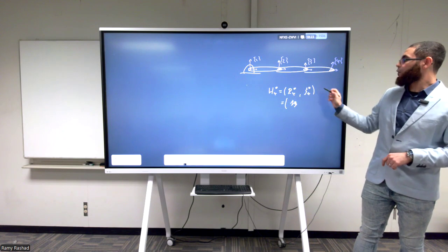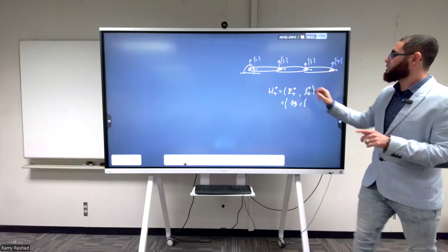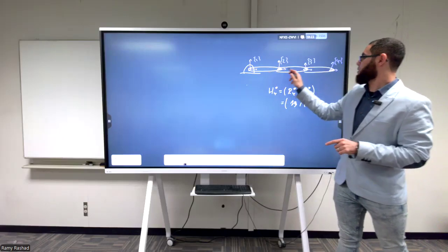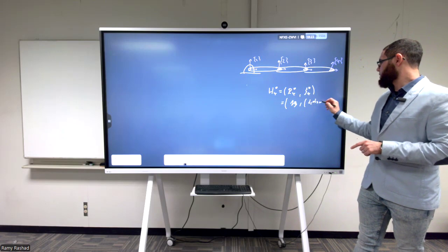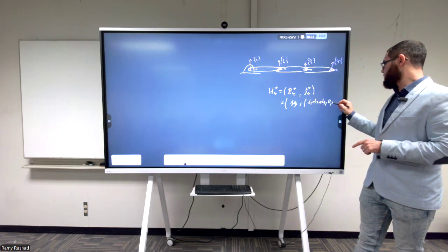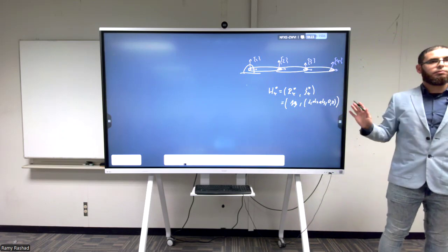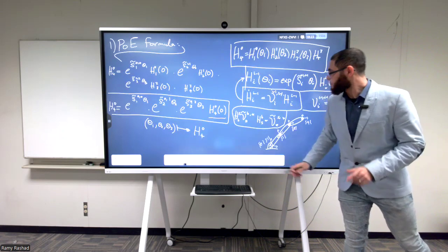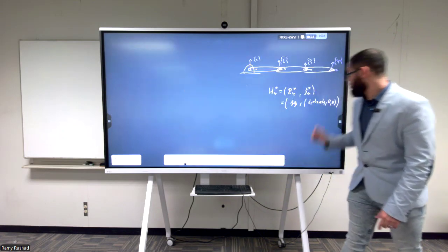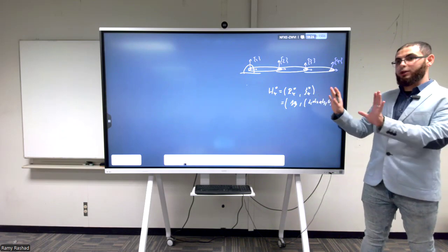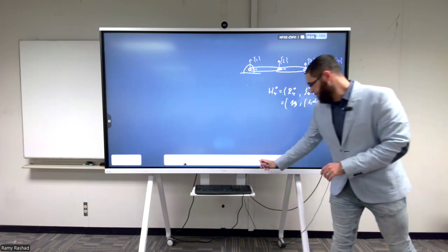What about the psi of 4 with respect to 0? It is 3 numbers. It's in this direction, L1 plus L2 plus L3, and I have 0 and 0. Clear? Let's go back. Because it's in 3D, we're going to be working everything with 3D because we're talking about homogeneous transformation in SE3.